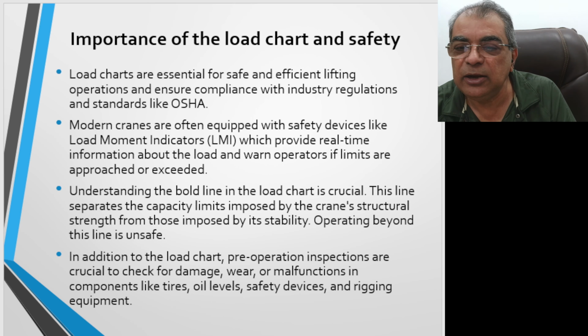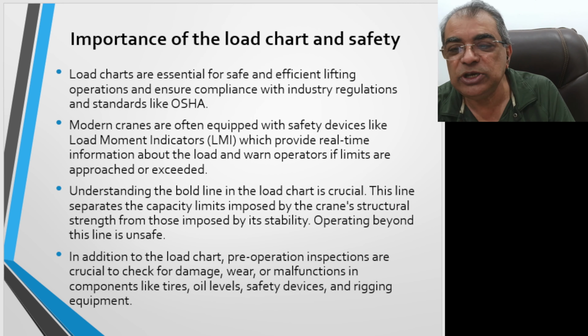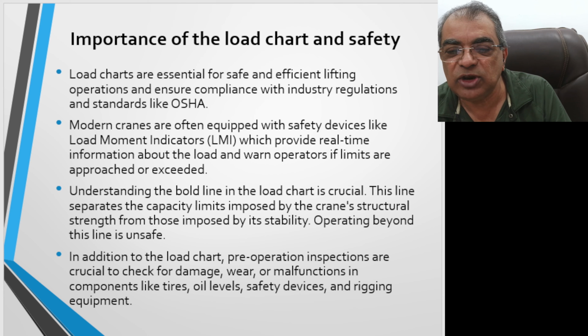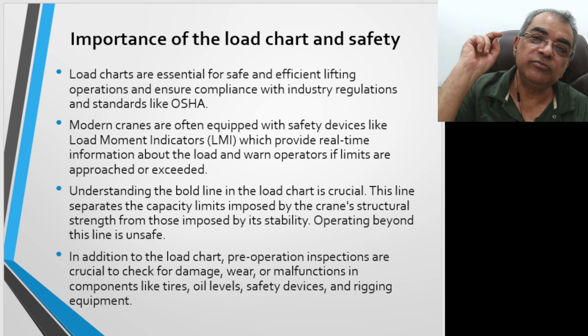Understanding the bold line in the load chart is crucial. This line separates the capacity limit imposed by the crane's structural strength from that imposed by its stability. Operating beyond this line is unsafe.